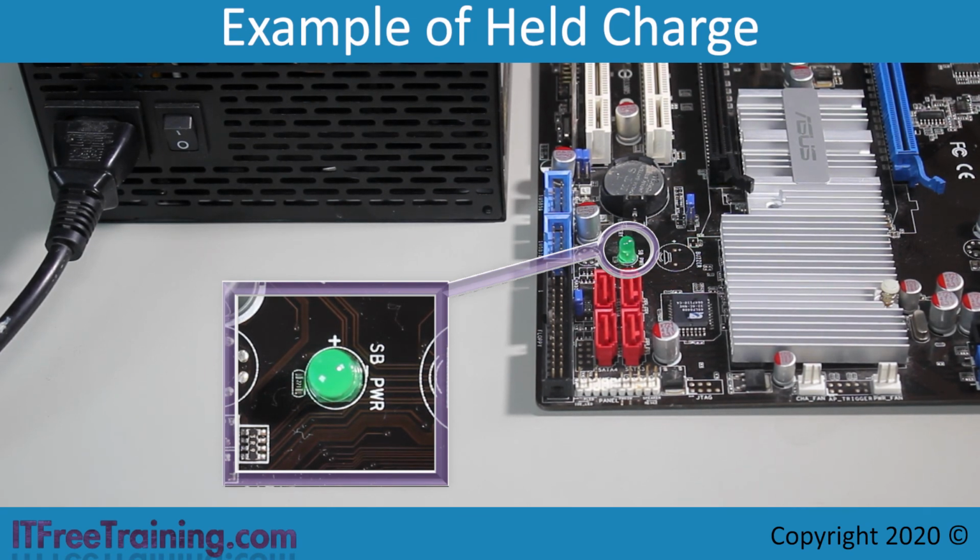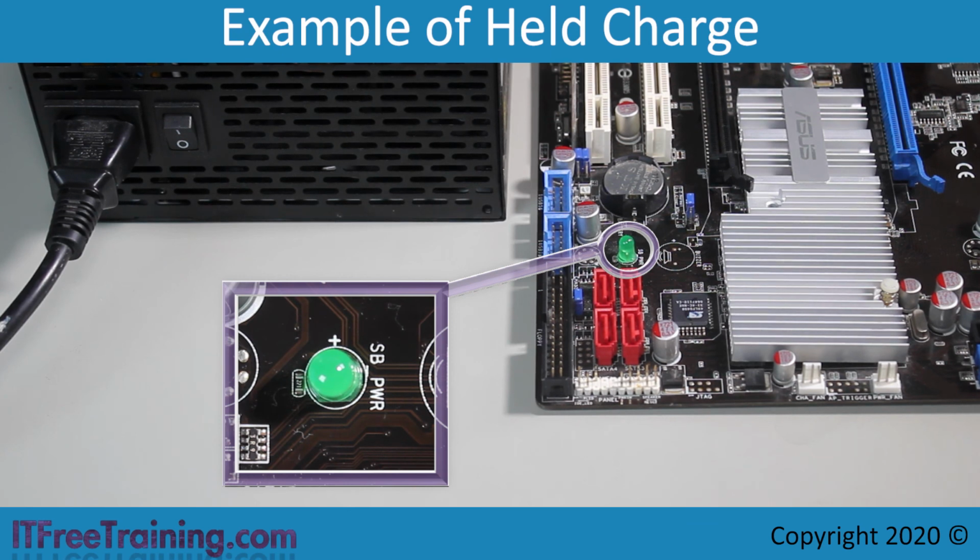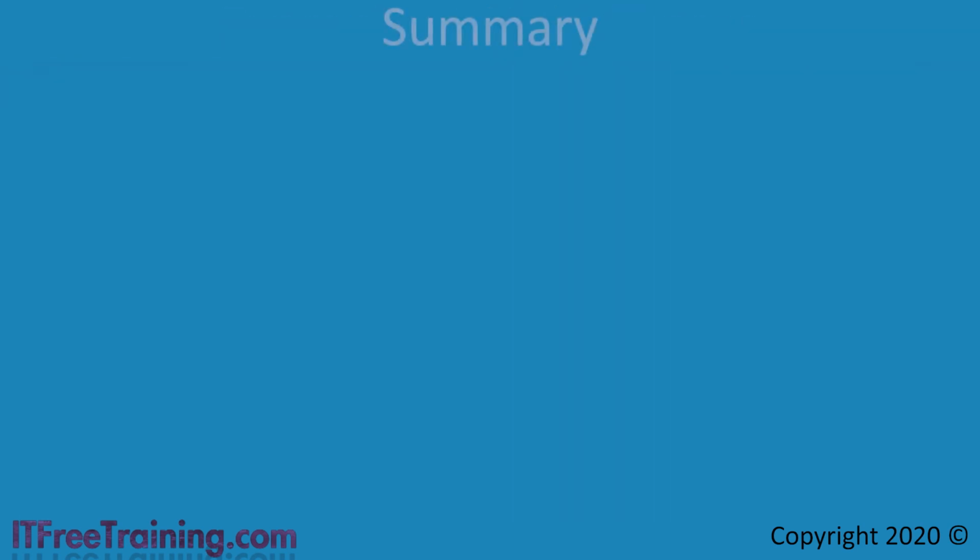Keep in mind that computer power supplies generate a number of different voltages, and even if the light is off, there is no guarantee that the power supply will not still have charge in it. Power supplies generally have multiple capacitors in them, and this single LED may not be draining them all. You can still get a shock from opening a computer's power supply. One trick that works with some devices is to switch them off, unplug the power, and switch them back on again. This will hopefully drain any remaining power, but you can never be sure this is the case.